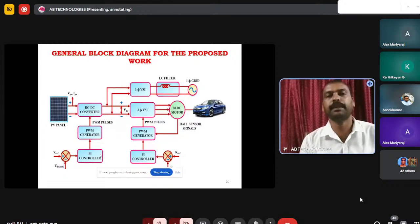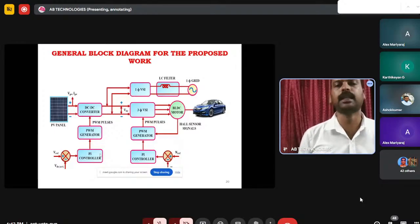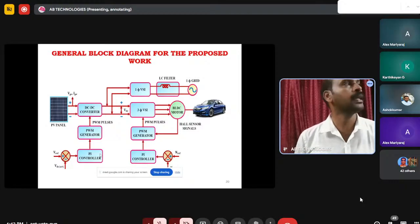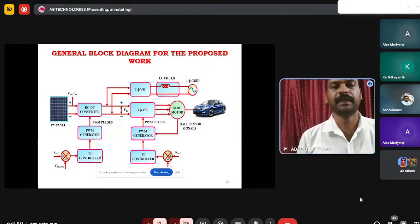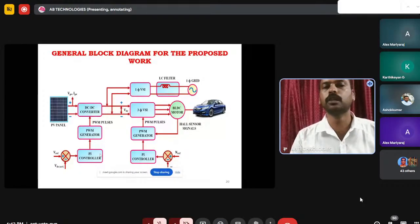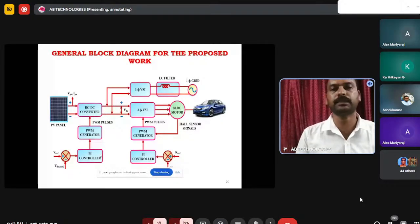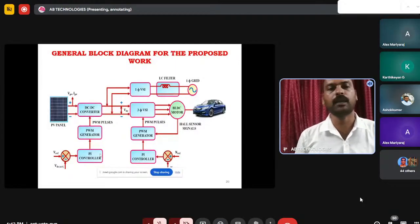So this is the difference between the MPPT algorithm and the closed loop algorithm. The MPPT algorithm is not an open loop system. That is also a closed loop system only. In the MPPT algorithm, you have to take the feedback from the PV side. But in the closed loop controller, you have to take the feedback from the output side. This is the difference between MPPT and the closed loop controller.